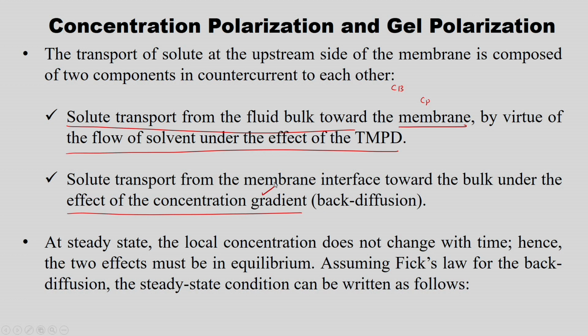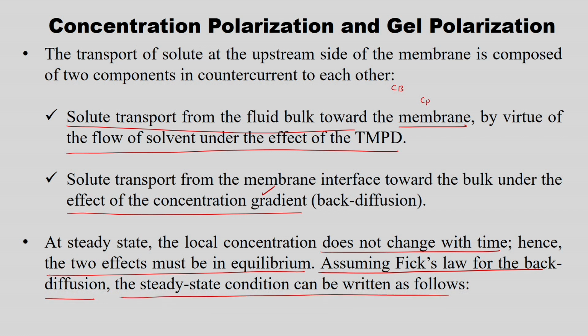This is what we probably told in the last lecture. The pressure gradient and concentration gradient both affect the separation process here. At steady state the local concentration does not change with time. So once steady state is reached, the two effects must be in equilibrium: the back diffusion as well as the convection of solute from the bulk to the membrane surface. Assuming Fick's law for the back diffusion, the steady state condition can be written as follows.